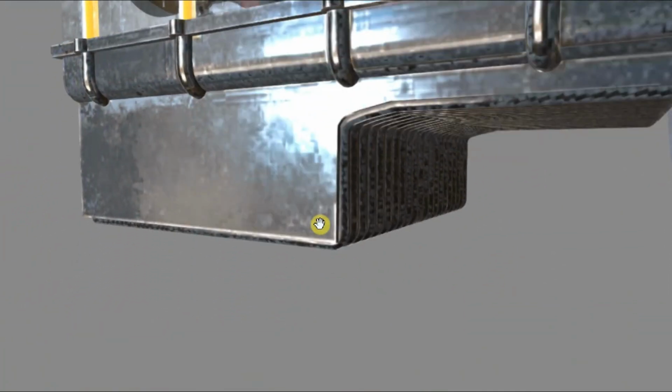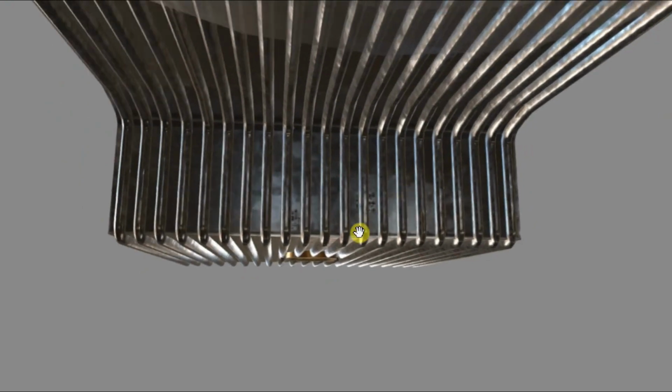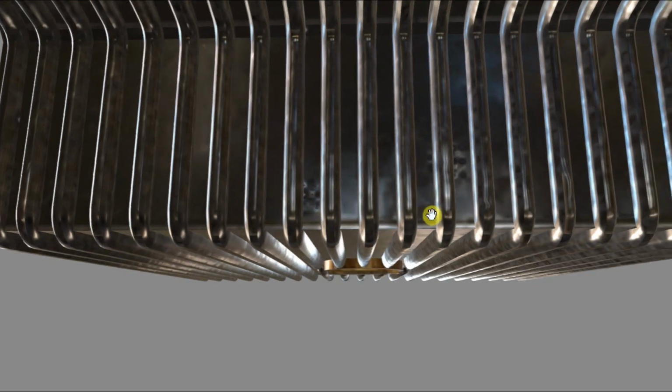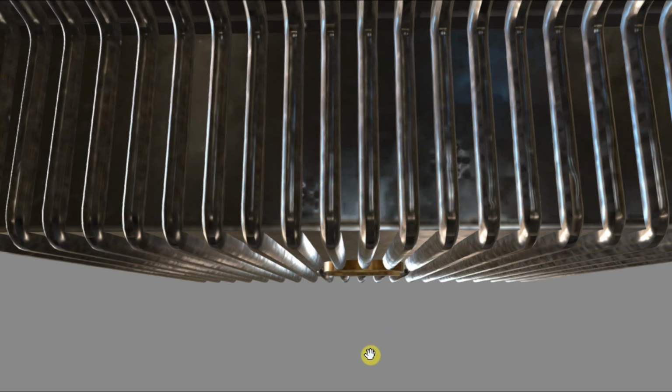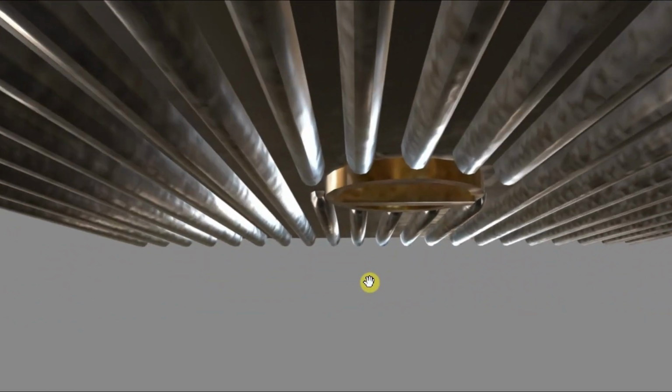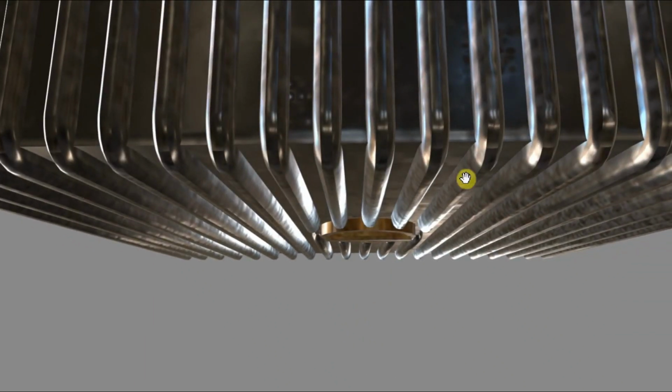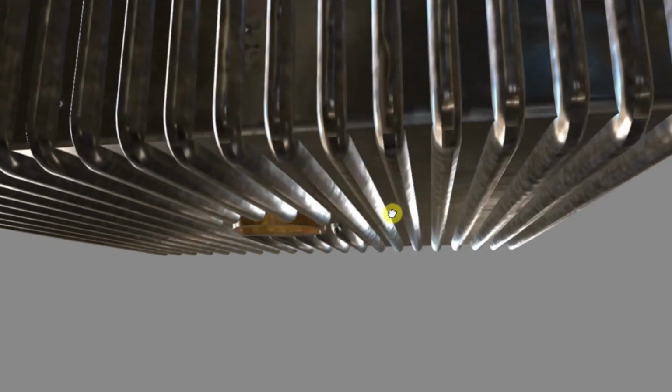Imagine for a moment that this engine was attached to a truck. You can see on the bottom here we have these squiggly shapes all along here. They allow heat to be transferred to the air very efficiently. So if this engine was mounted in a truck and the truck was travelling forward, such as in the direction we're travelling now, then the air is going to be passing across these fins, these cooling fins, and we're going to be cooling down all of the oil in the oil pan. If we do that, then that means that the oil temperature will reduce, and when we recirculate it around the engine again, we're not going to cause the engine to overheat.